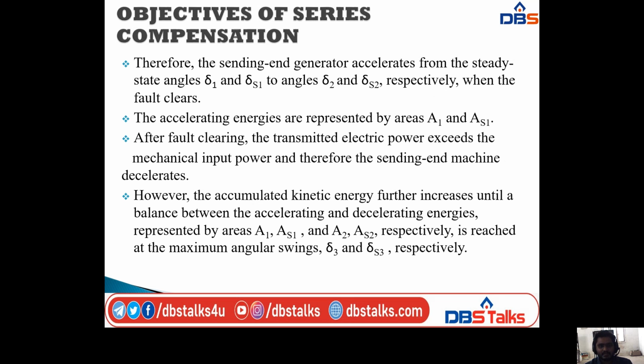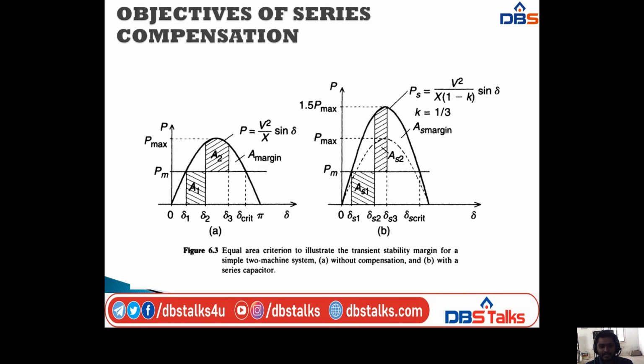Therefore, the sending end generator accelerates from the steady state angles delta 1 and delta S1 to angles delta 2 and delta S2 respectively when the fault clears.